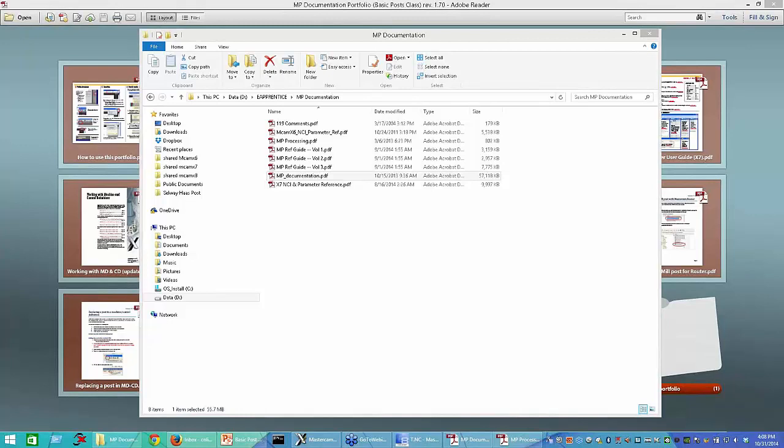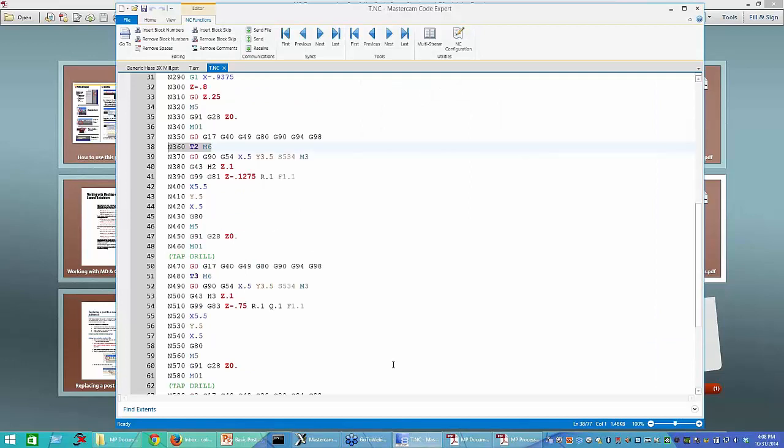And let's see if we can move through this. And again, Colin, you'll have to decide what you can show quickly and what's just a little bit too in-depth for this. So Nelson's asking, he would like to have a G28 X0, Y0 at the end of his program. Say that again, Derek. He'd like a G28 at the end of his program? Yes, with an X0, Y0, or at least with a Y0. The X doesn't necessarily have to move.